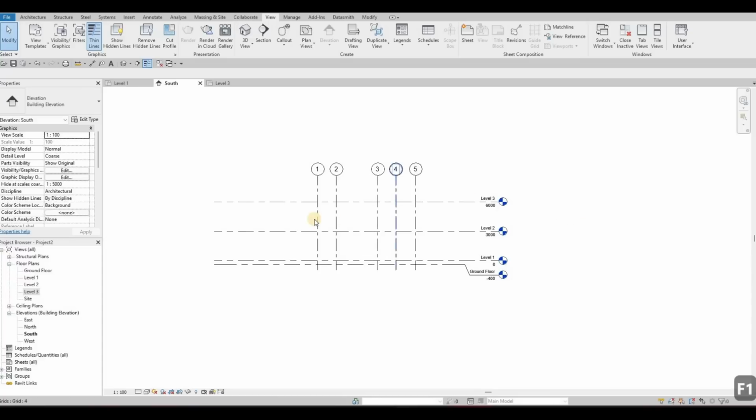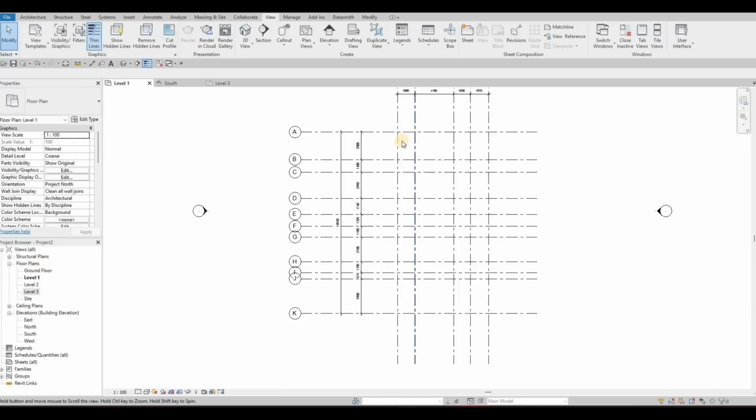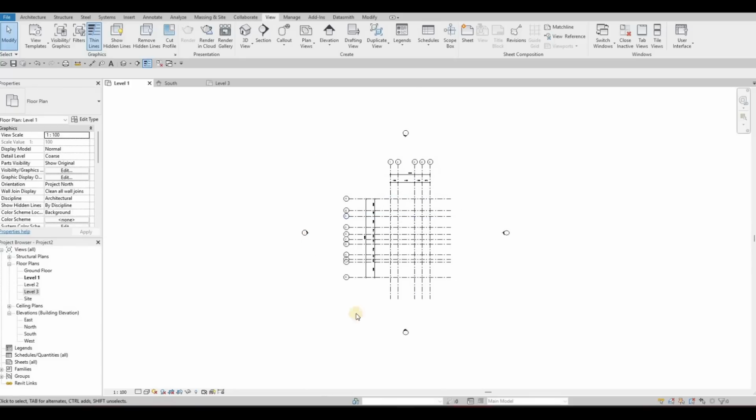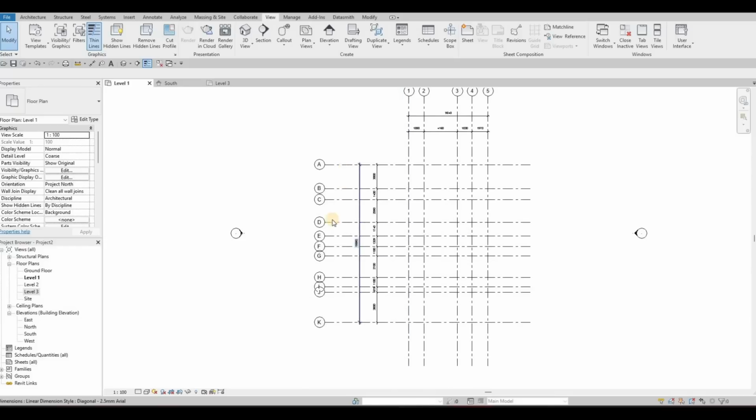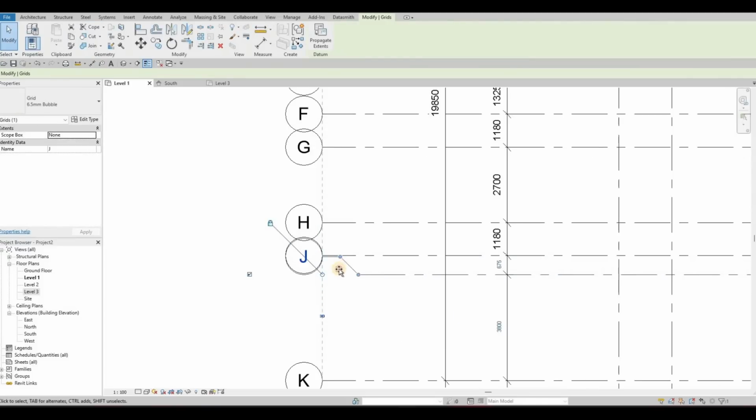So we have now added levels with ground floor, and what we need to do is go to level 1 again. We're gonna touch the ground floor later on, but here now on level 1, we double check that our grid lines or our elevation tags are added, and then as you can see, if there is some grid lines that are overlapping, you can also create an elbow, and then you can push them either on this side or this side.